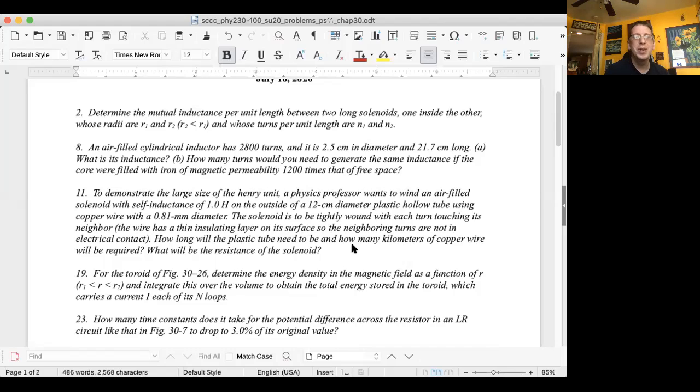So there are a few steps here. So you know the diameter of the wire, and so the length of the solenoid is equal to the total number of turns multiplied by that diameter. So you start with that and figure out, well, how many turns is that going to be? And try to figure out, well, how do you find N? And if you do that, you can answer the first part.